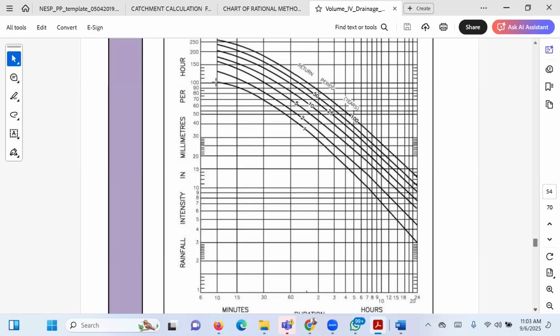This cuts across whatever the hydraulic structure, like one of our engineers said, whether it's a retaining basin, an overflow structure, or a primary sedimentation tank for your treatment plant, all these things are factors. In Nigeria, we don't treat stormwater, we don't have stormwater facilities. But in developed countries, they have different overflow structures because they don't want the city to overflow. Some places that are prone to flood have huge reservoirs underground. When the flooding exceeds limits, they open the underground infrastructure and the water just flows there. Then after a while, they do a controlled release.